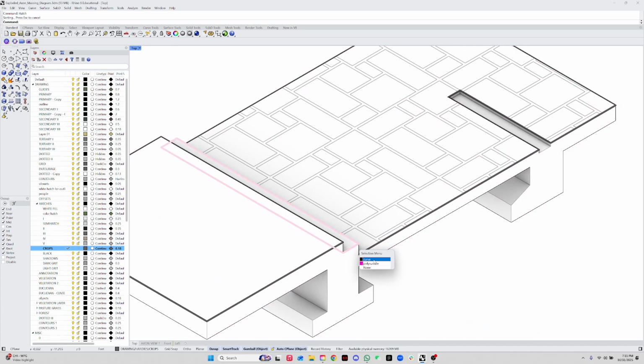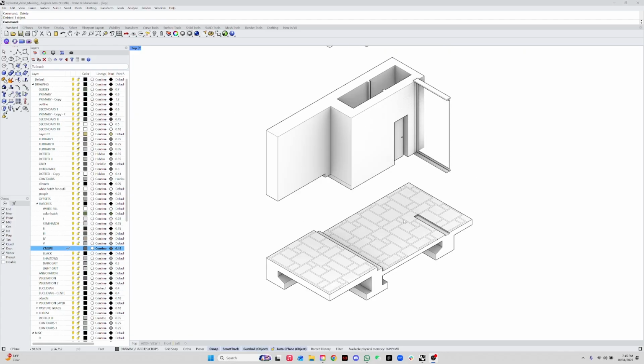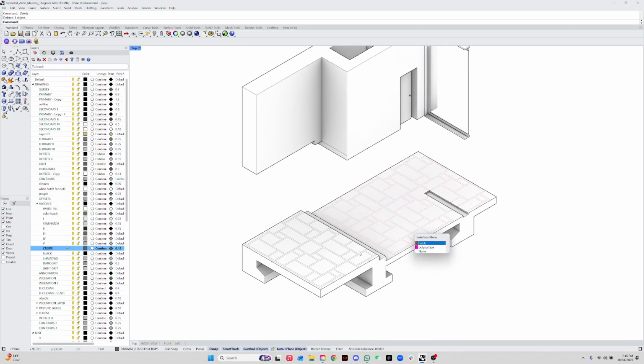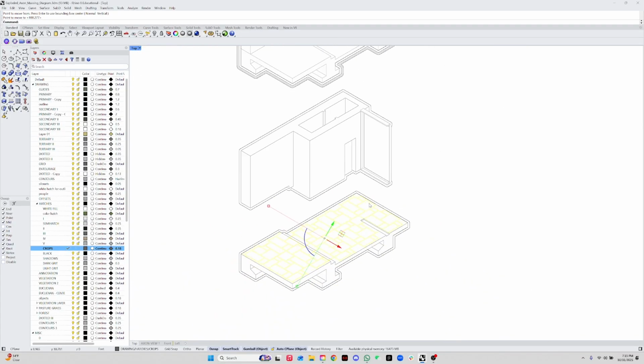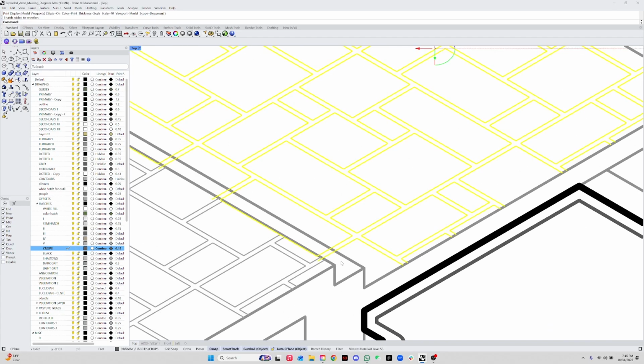Do the same thing here. Or maybe I can leave that one blank and then just do it on top of the surface, right? Since that's just a stair step. I'm going to do that. I'm going to get rid of that line. Don't need it. Okay, now that I have the hatches for this, right? So I have this one here and this one here. Now when I move those into here, I'm going to turn my print display on. Okay. So now I have this little problem here where the hatch is going over.